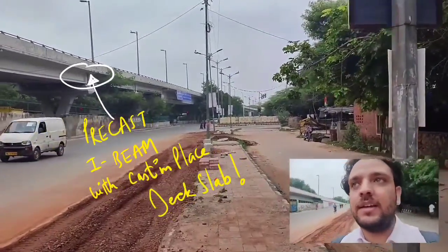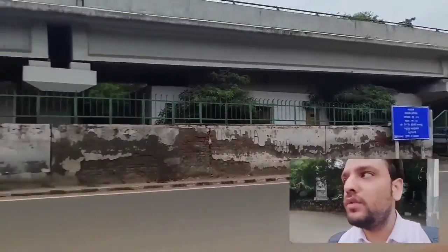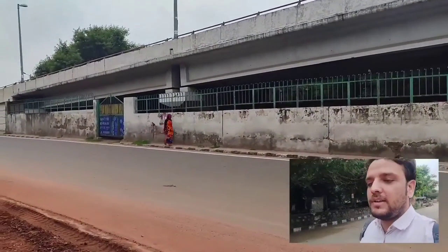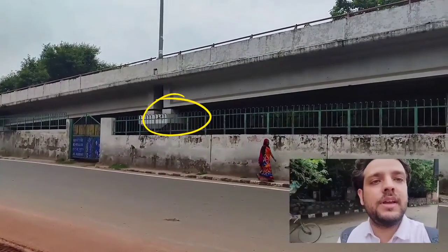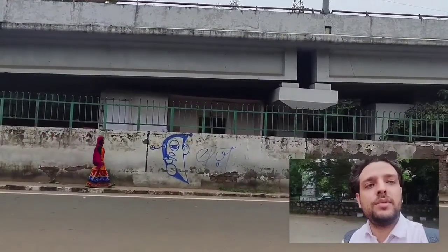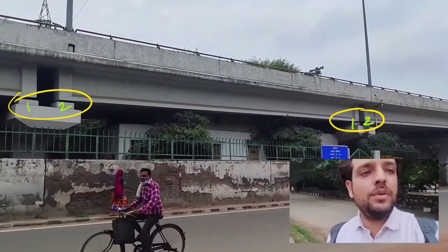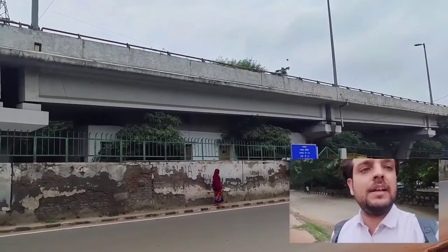That is the reason I am standing today in front of this flyover. If you see, all the spans are simply supported. I had already shown you how we can decide whether a span is simply supported or not. See this pier cap, 2 bearings in the longitudinal direction are present, and on the adjoining pier cap again 2 bearings in the longitudinal direction are present. And if you see by this view, if I consider this span, 2 bearings in the longitudinal direction are present on each pier cap, and hence it is very certain that this is a simply supported structure.